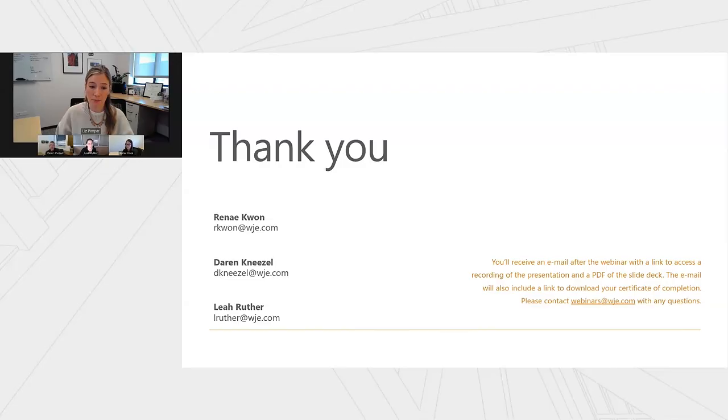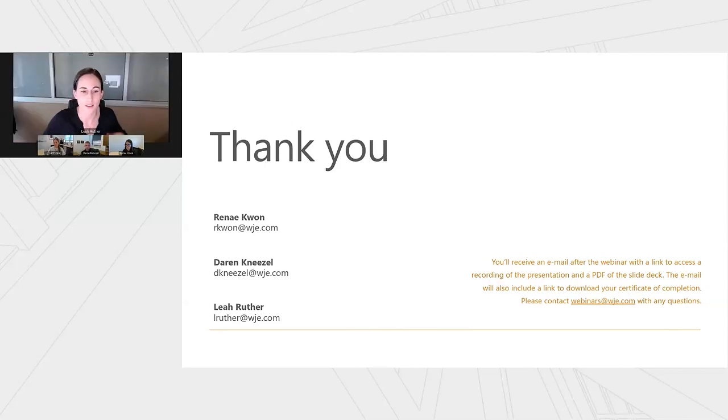Yeah, so the code limits it, I think it was 720 square inches. And I think once you get past that 360, you need an installation procedure. And so I think the recommendation is to make sure you're back buttering the units and then potentially having a couple folks, not just one person with the install, to make sure you get that nice mortar squeeze out around the perimeter. And that's where those mock-ups and preliminary procedures are helpful for a good installation.